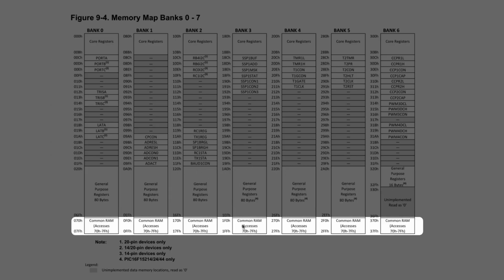But the CBR, or common bank registers, are the same regardless of the bank that you're in. Now this is super useful if you have data in one bank that needs to be transferred to another bank. Now we're not using it for that purpose right now. We're using it for an entirely different reason, and it's more personal, I'd say.